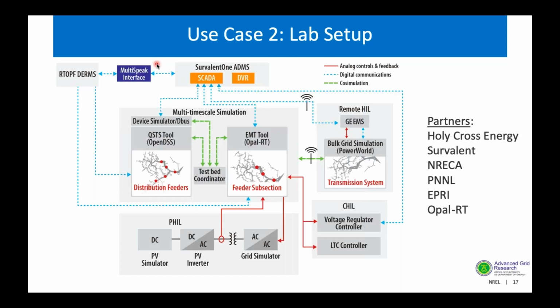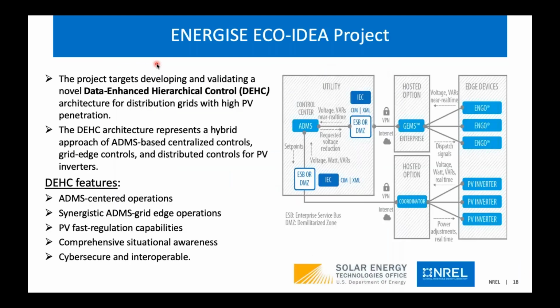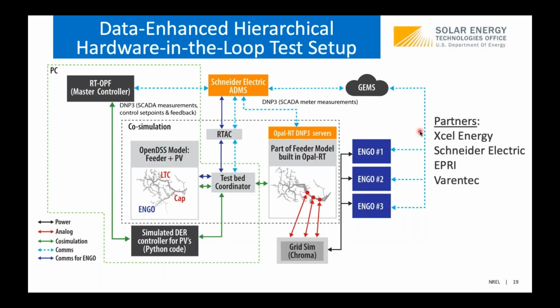And then I'll mention just one more. In this use case too, we had an ADMS and a DERMS. Here we have an ADMS. We use another variation of NREL's DERMS code, but then we also include Varentec, which has end-of-line solutions to boost voltage at the end of the line, and coordinators. So these three control systems are all working together.